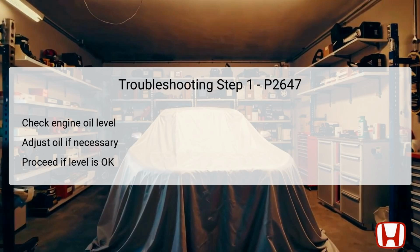The first troubleshooting step involves checking the engine oil level. A proper oil level is crucial, as insufficient oil can lead to incorrect readings from the rocker arm oil pressure switch, triggering DTC P2647. Use the dipstick to verify that the oil level falls within the recommended range. If the oil level is low, it's essential to add the appropriate type and amount of oil to bring it up to the correct level.